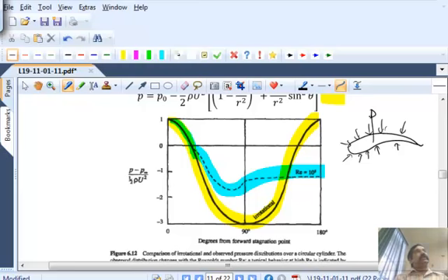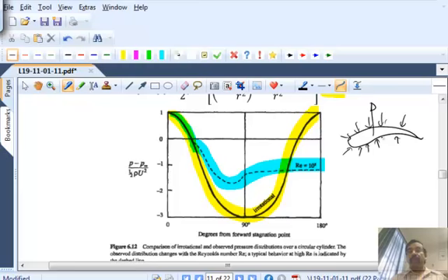If I resolve it in the vertical direction, that will be the lift force, and that prediction is very accurate for these kinds of shapes of objects. But for cylindrical objects like this, as you can see, the error is already large between the actual pressure field and what is calculated from the irrotational flow.